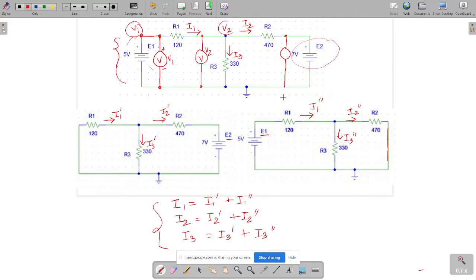And how about V3? If we consider V3 is over here, how do we connect the voltmeter? Now I think it's going to be your answer. The positive terminal will be connected after R2, and the negative will be connected to the ground. Okay, so this voltmeter will show the value of V3. Now do we all understand how we are trying to solve all the node voltages, or how we are trying to detect the node voltages?